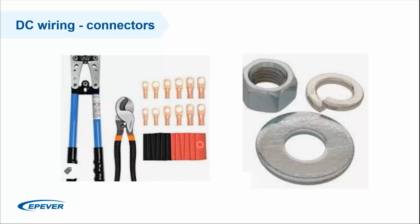So if you do not cover it with the shrinks, then in time the cables will corrode, and this corrosion will increase the resistance again, and then it will get hot. So even very small parts of your installation will matter.